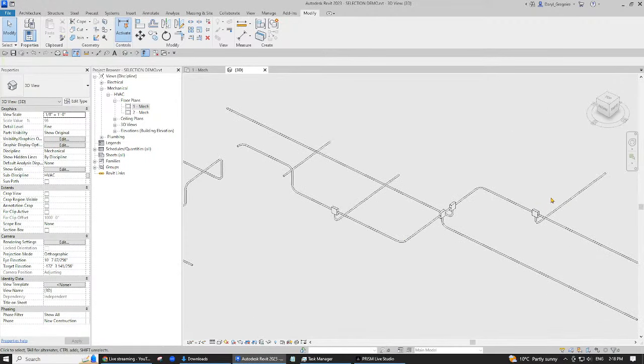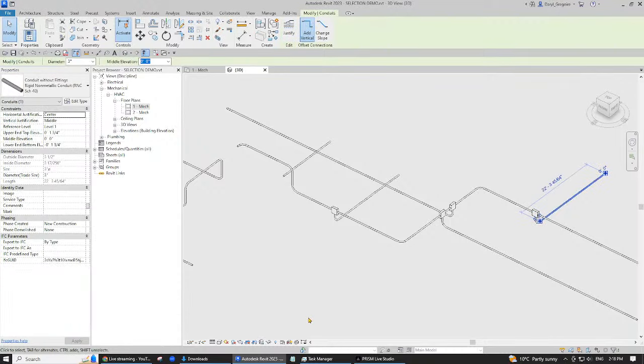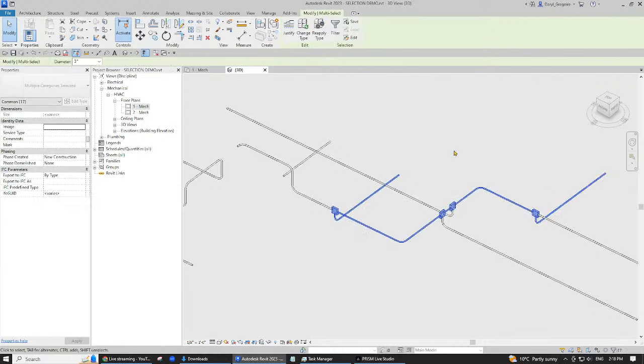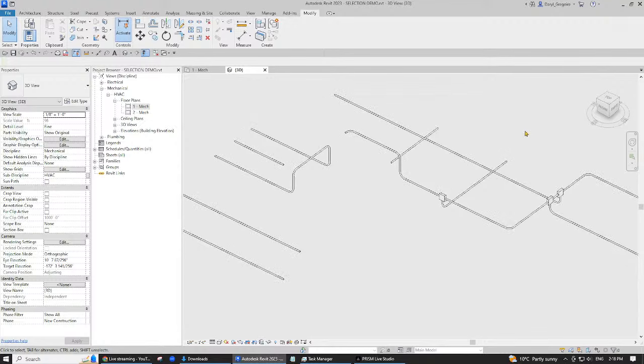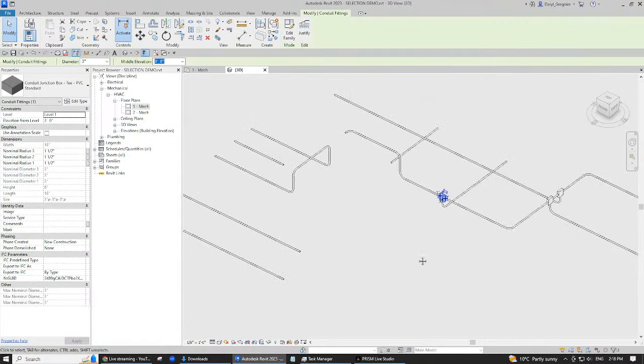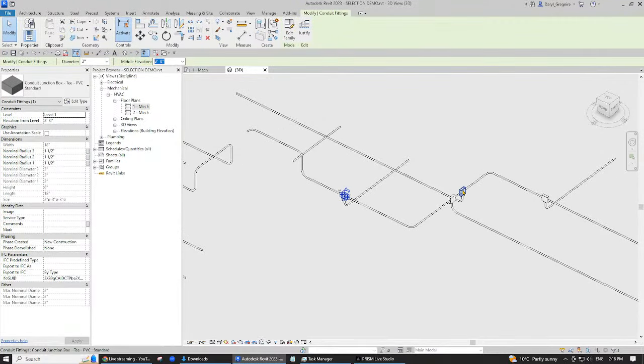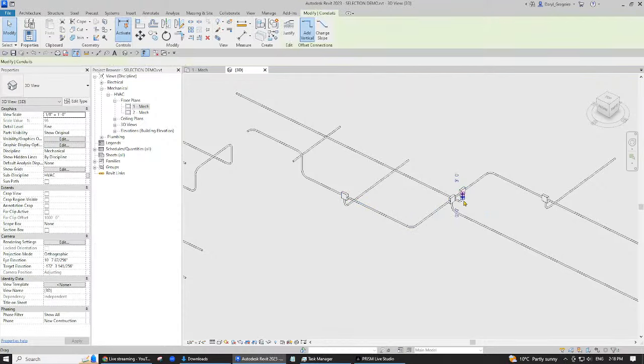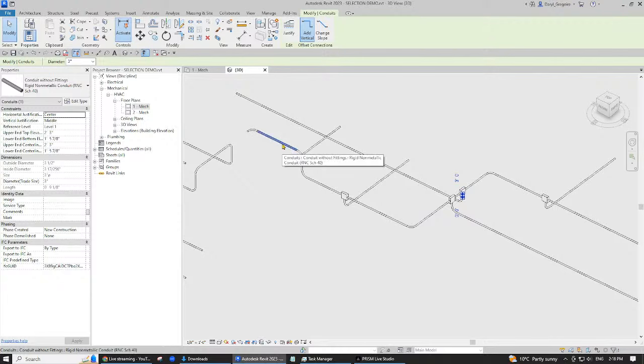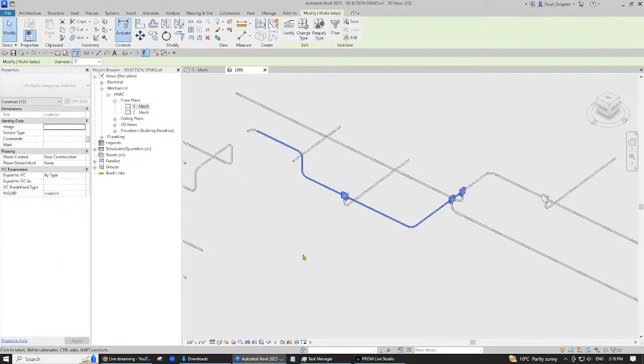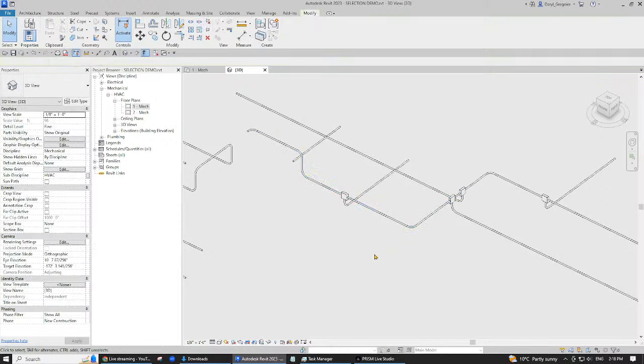Okay, go over to here. Pick this piece, hover over this, hover, tab, click, and it'll pick between those 2 points, right? So pick this junction box, hover near here, tab, click, or pick on here, hover, tab, click. It'll pinch between those 2 points. And then after that, you can do a control or whatever you want with your selecting, tabbing.